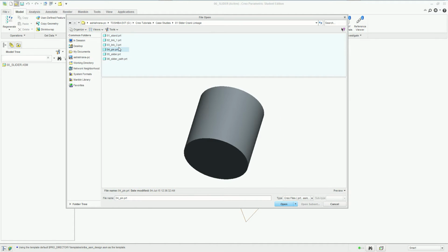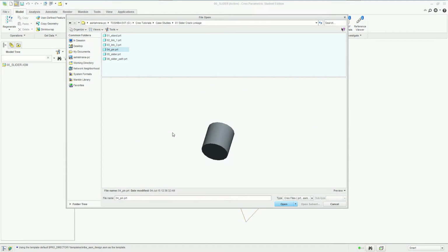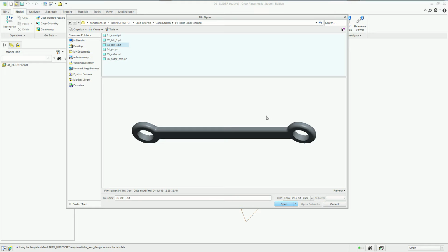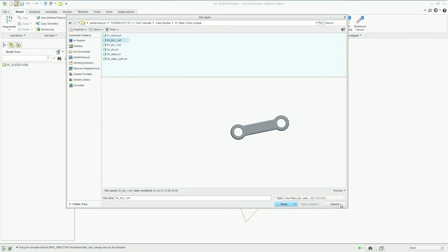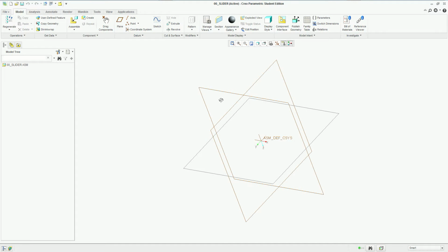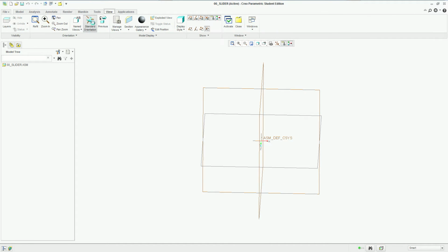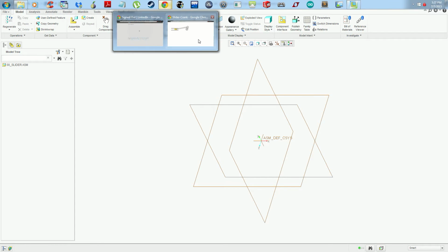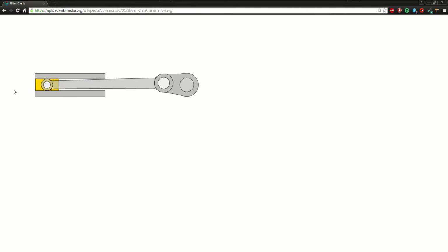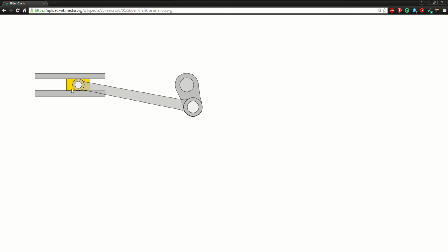So just make sure it makes sense physically, and just like that, the diameter for this pin is the same as the diameter in these holes for the links. Things like that. They're pretty straightforward. Just want to mention them anyway. I'm gonna go to the default view right here, and I'm gonna begin. So I already have this subassembly made. And in this subassembly, I'm gonna make a slider component of this main assembly right here.